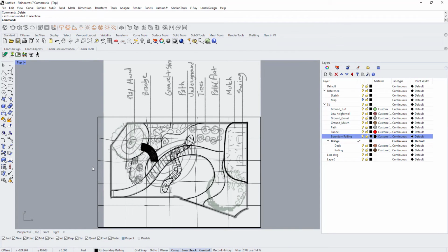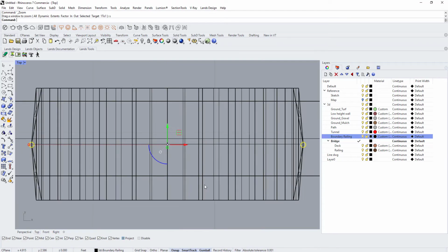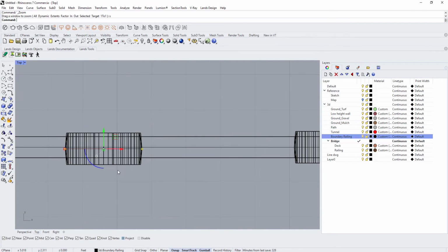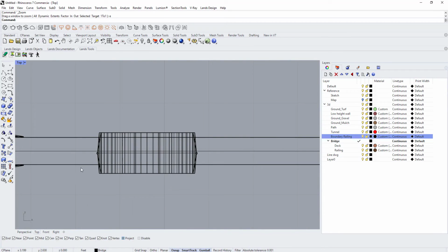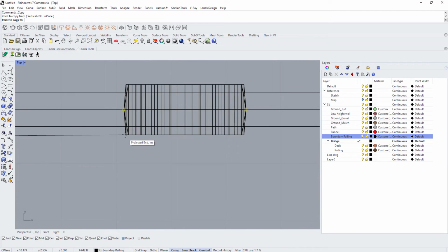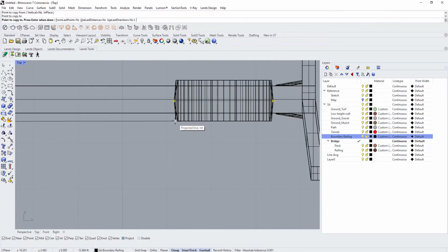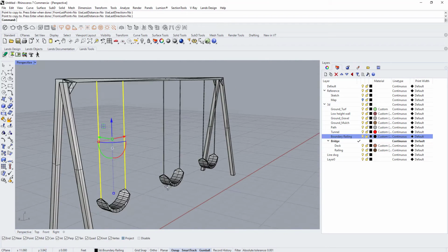If you can't see an object in any specific viewport, you can always press Z space S space for zoom to your selection. Z is for zoom, S is for selection. And if you want to see everything in your model space, you just press Z space E space for zoom to extents all. So that's something to be kept in mind while importing stuff. And then copy your pipes to different parts of the model, and you are set to go.